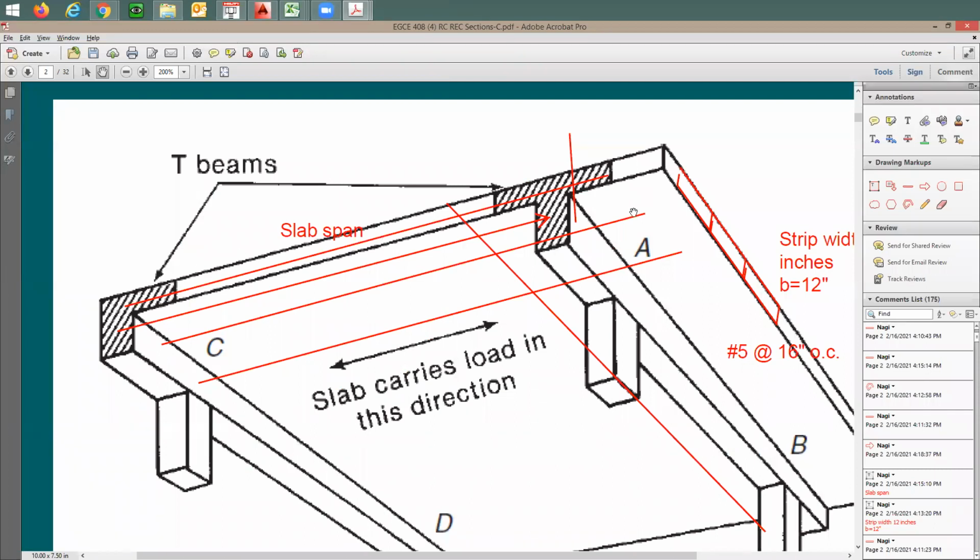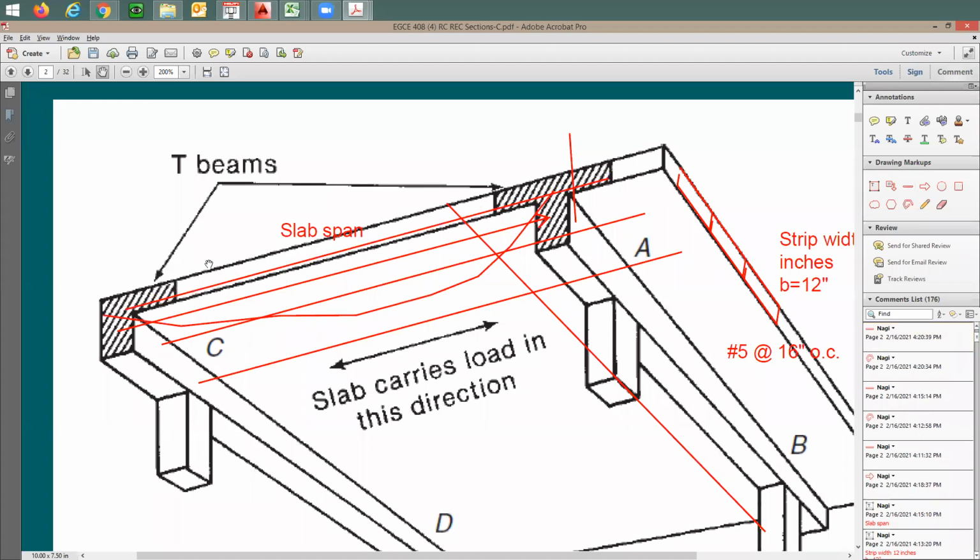And when the slab is going to deflect, it's going to be coming down this way. Just think about the deformed shape for this slab, just exaggerating here. Right? It's going to be down. Which means the bottom reinforcing is what we really need in this simply supported span. Why? Because we have positive moment. Tension is going to be in the bottom, compression is going to be in the top. So I need the bottom reinforcing.